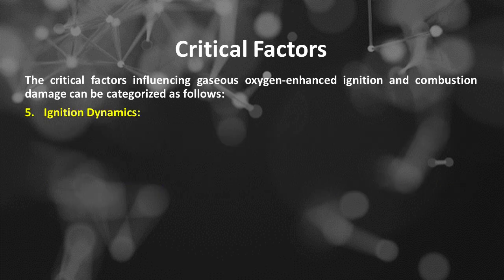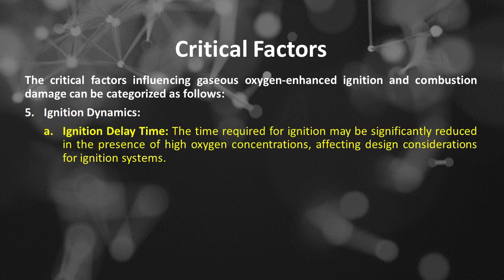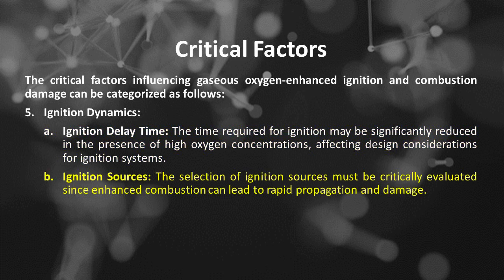Category number 5 of the critical factors influencing gaseous oxygen-enhanced ignition and combustion damage is ignition dynamics, which includes: A, ignition delay time. The time required for ignition may be significantly reduced in the presence of high oxygen concentrations, affecting design considerations for ignition systems. B, ignition sources. The selection of ignition sources must be critically evaluated since enhanced combustion can lead to rapid propagation and damage.